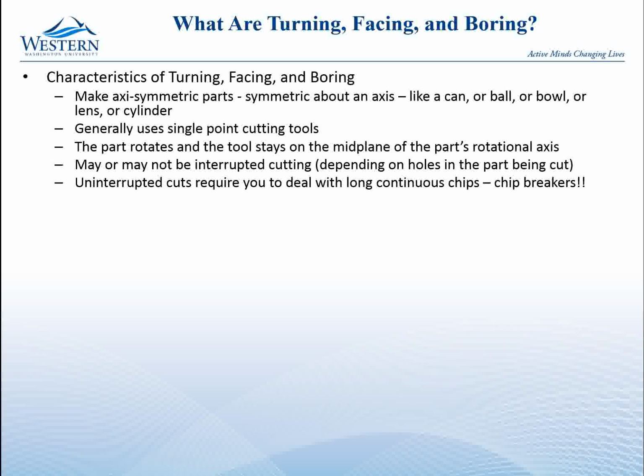Sometimes there's interrupted cutting, sometimes not. It depends on whether there are holes in the part or steps or slots or any pre-existing features. Also, when we start cutting, it's often not exactly centered, and so as we start cutting, the cut won't cut all the way around because the part isn't centered well. If you have uninterrupted cuts, then you get extremely long chips, and we'll do some calculations, I think, that will talk about the length of the chips, and they're surprisingly long. Anyway, you have to do something to deal with those chips.